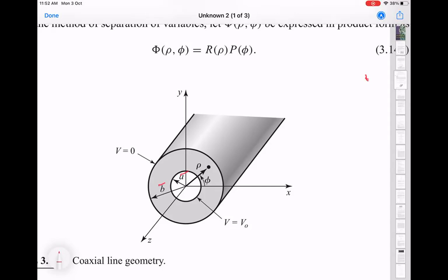not shown here. Now the center one is a solid, usually. It can be hollow, but it cannot be hollow from the cross-sectional side, in the sense that you cannot have this surface also be hollow, because then you actually have a tube, which can support its own modes, right? If there is a gap there. But from the point of view of the transmission line, it's still the outer surface. So one could have a tube, but remember that it's much smaller, so it will have a cutoff frequency which is much higher. So that will not support a TEM mode.